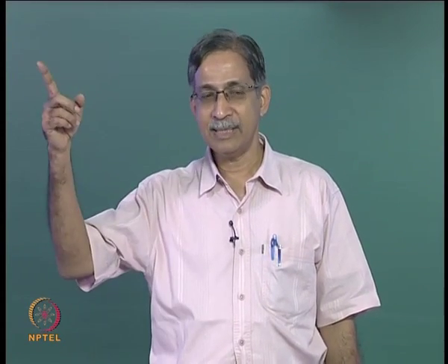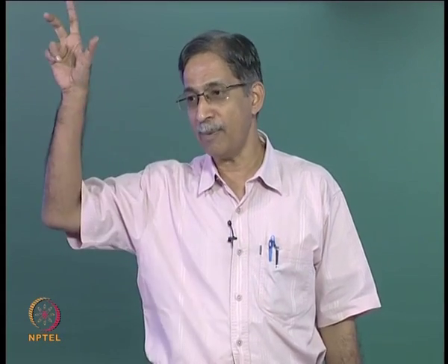Is it a sinusoidal shape, etc.? It does not tell you anything more than that, which means it tells you, let us say, at the mid height of the column, what the deflection is in relation to the top. Those ratios are maintained. That is what we call a mode shape, and the first mode shape looks like this.